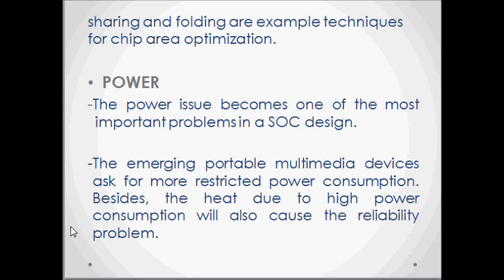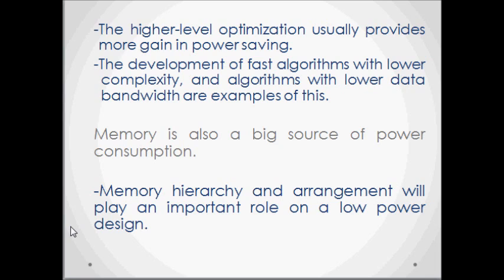Power. The power issue becomes one of the most important problems in SoC design. As process develops, a chip can provide more and more transistors but allowed power consumption in chip will not increase. The emerging portable multimedia device asks for more restricted power consumption. Besides, the heat due to high power consumption will also cause reliability problems.